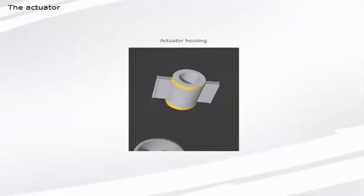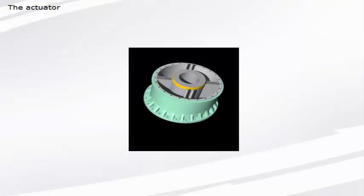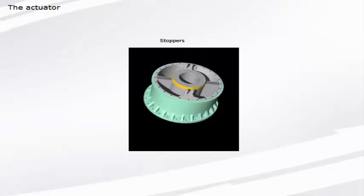This is the actuator housing. These are the stopper mounting bars. These are the stoppers, which serve a dual purpose. Together with the rotor vanes, the stoppers divide the actuator into pressure chambers, and also make boundaries for the maximum rudder angle. This is the lower packing gland.